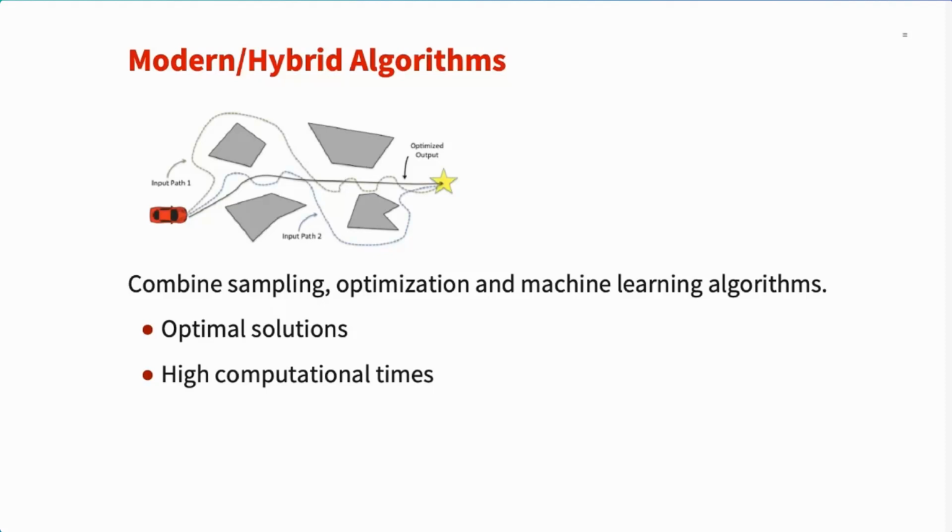So in these algorithms, an initial collision-free path is generated using the sampling-based algorithms, and then this path is used as the initial condition put into the optimization-based algorithm in order to obtain the final, most optimized trajectory. With this procedure, it is possible to plan a final optimized trajectory because of the optimization that is run after the sampling-based planner.